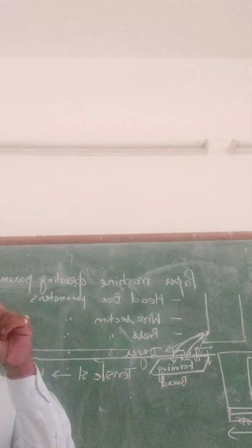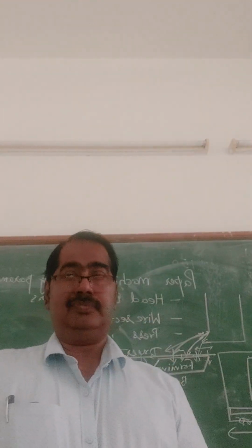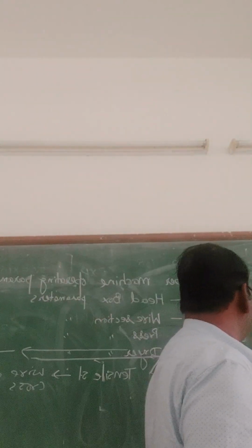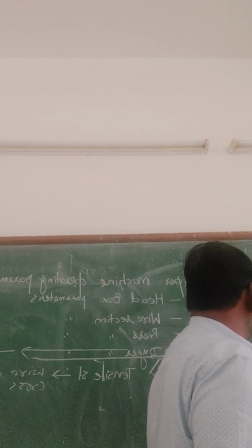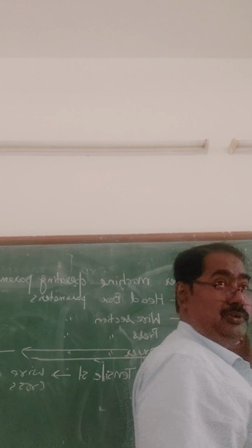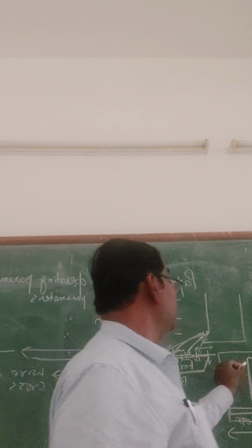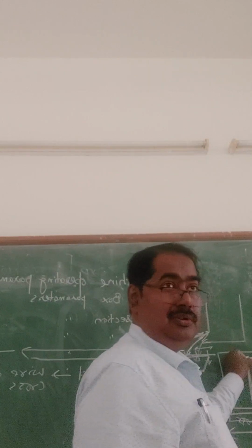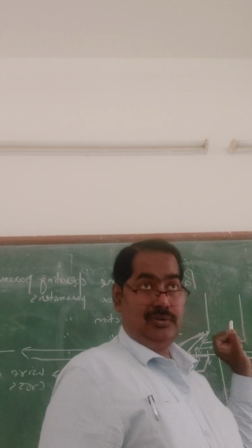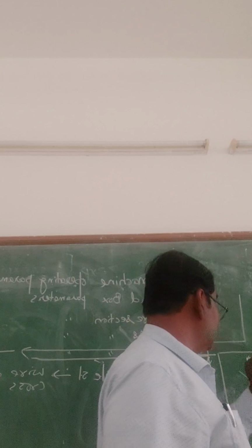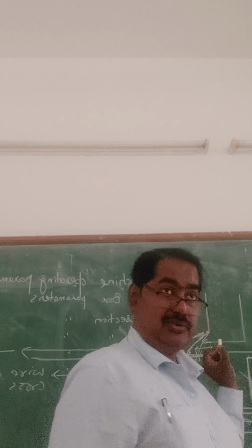Whenever the sample is taken in rectangular form, it has one dimension more than the other. Like here, in case of tensile, mostly length will be taken nearby 15 centimeter and width nearby 1.5 centimeter only. So it depends on which direction the length is taken from, machine direction or cross direction.